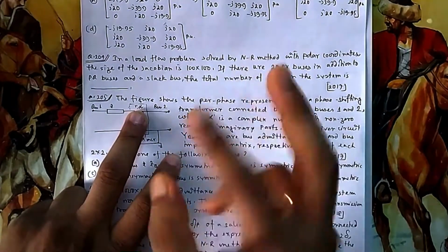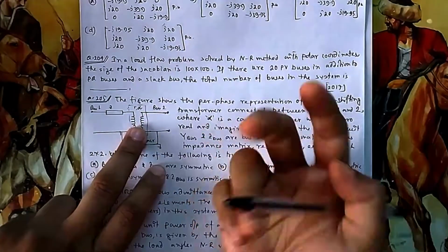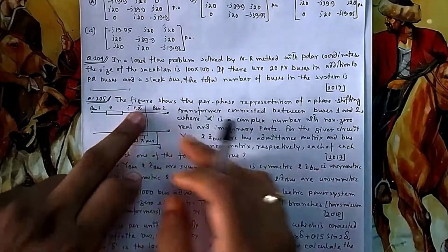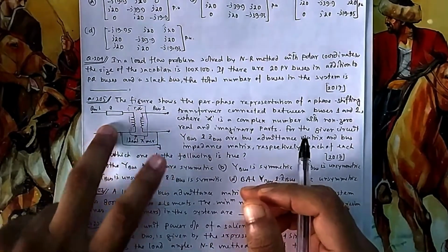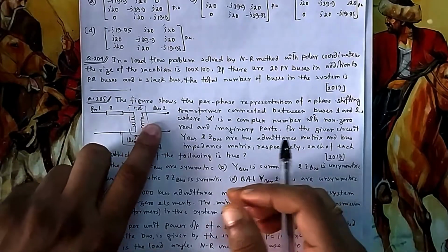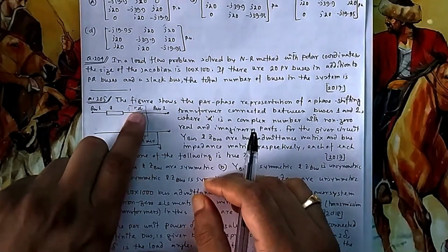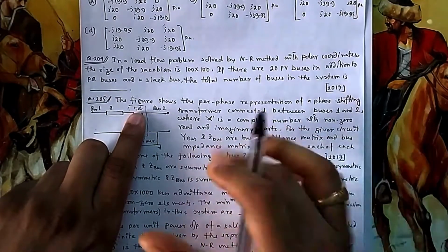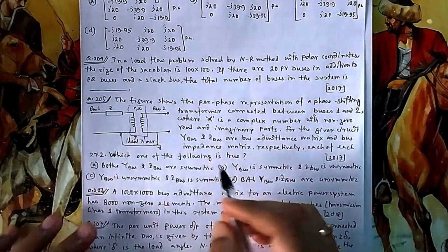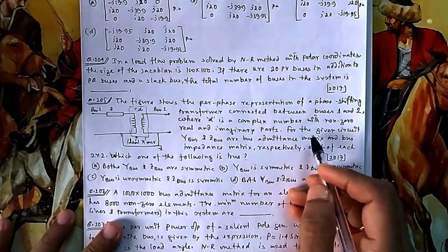So the ratio is also multiplied, so voltage will get 2 times, and angle will also change by 30 degrees. That is the meaning of alpha becoming a complex number. Normally in a transformer 1:3 means we multiply the voltage by 3 times. But here angle will also be added, like 3 angle 10, 3 angle 20. That is the phase shifting transformer.